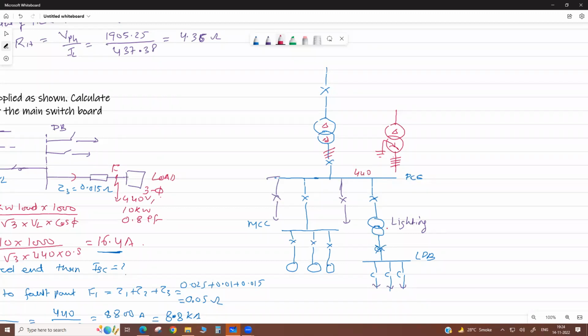With the lighting transformer we reduce it; the lighting transformer is 440 by 220 volt. So between any two phases we get 220 volt. So on board, we feed the light with 2 phases, but it is 220 volt. Okay. Correct. So this is the purpose of the lighting transformer.